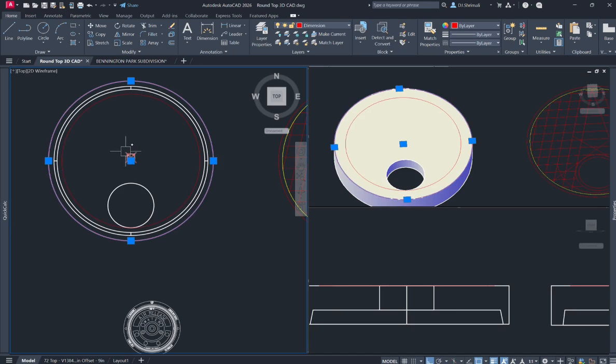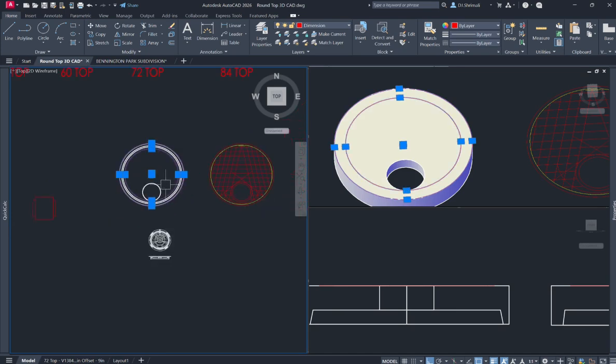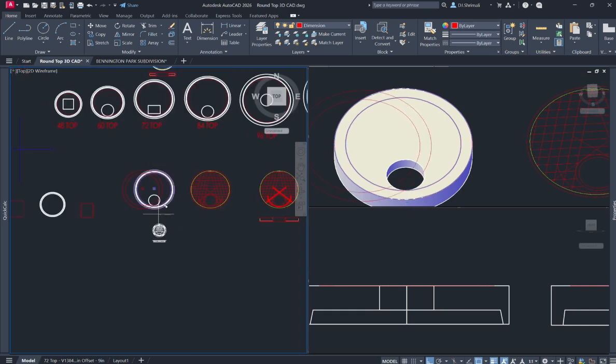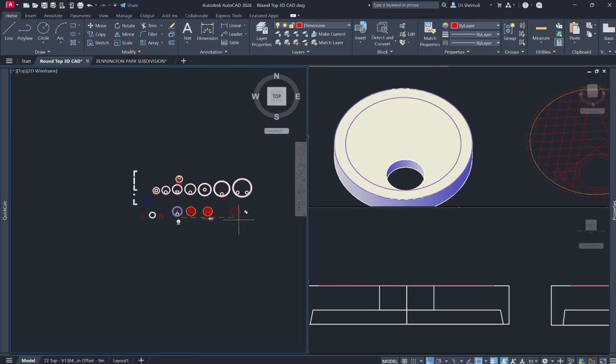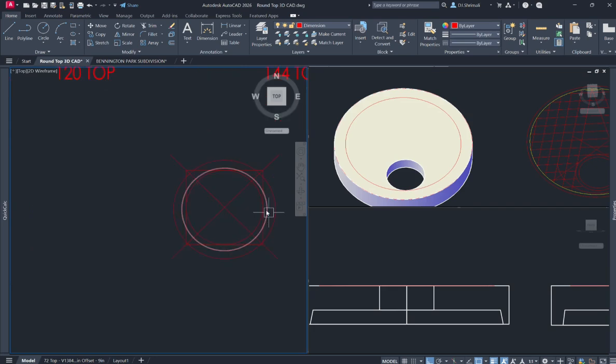So that will be your centroid. Okay, and then you will just move the circle or create a circle and put that at the centroid. And you can select the point visibility or looks using p-type command.